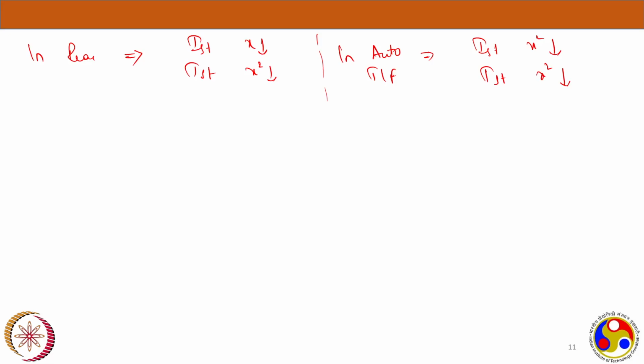That's why there is another nice method, which is the star delta method. No need to buy any components like a reactor or auto transformer, but still you can get the reduced current just by changing the winding of your stator from delta to star. So you have to switch between star and delta for starting. That's the reason for calling this method like that. So there comes the importance of the next method.